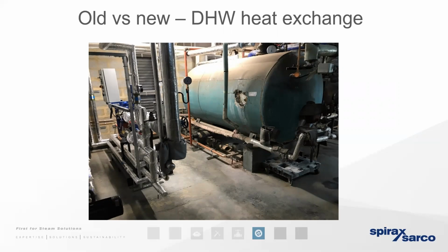If we're generating 2 to 3 times more hot water than is ever going to be required by the process, there's a huge inefficiency there. And with a huge solution, not only the water, but also the body of the heat exchanger, because of the mass of steel, is going to be radiating heat energy out into the plant room. It's going to be taking up a significant footprint of space in the plant room. So we've got a sizing inefficiency there.